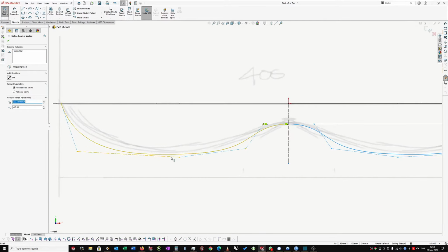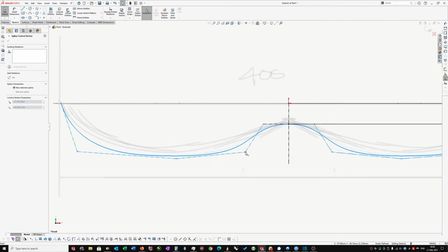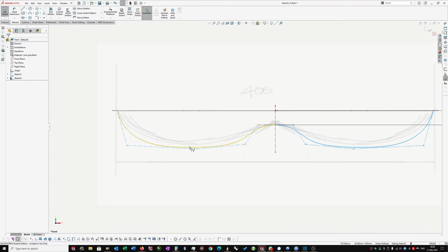Alright, so like I've done here, I want a position for this curve, and I'm going to leave this Bezier curve a little bit deeper than what I've drawn, and that's because I in fact want a little bit more meat on this surface when I make it, so that I can trim it. And I'm going to make this a little bit steeper for the same reason. Okay, and then grab hold of a point and put it in some position which is sort of in the middle, but it's going to mark the lowest point of this curve.